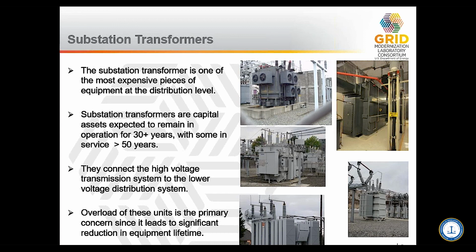And so what you'll often see is that transformers, when they first go in, may be lightly loaded, but over time, due to load growth and various changes, they may experience various overloads at different points in their time, and that will affect their lifetime of the equipment. And so this is where there's a lot of work that goes on in the planning arena. What's the proper level of loading, asset management, and this ties into a lot of other central issues in power system operations. Next slide, please.